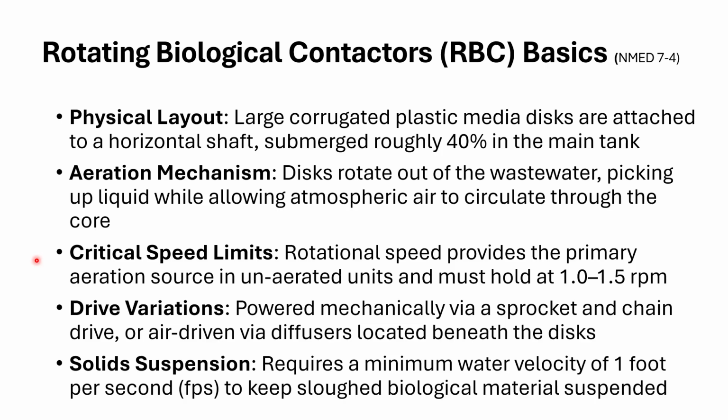And remember, the drums are providing aeration. They're also providing the method for that film growing on the corrugated plastic discs to dip down below the wastewater and take a chomp of food before they come up for air, and they metabolize that. They're very slow moving. They're going to have about one revolution per minute. So they're very slow moving discs or barrels, okay?